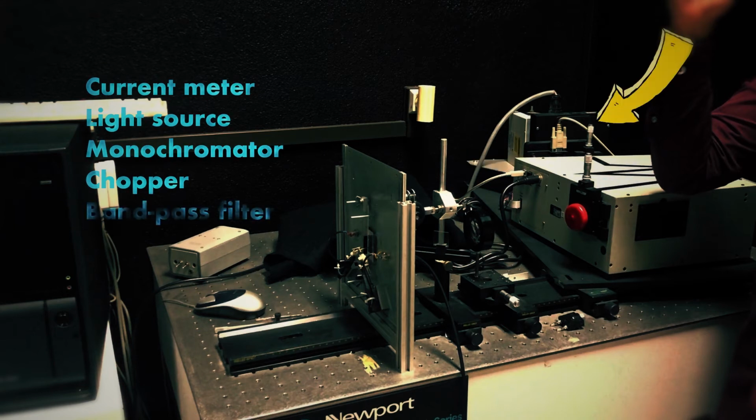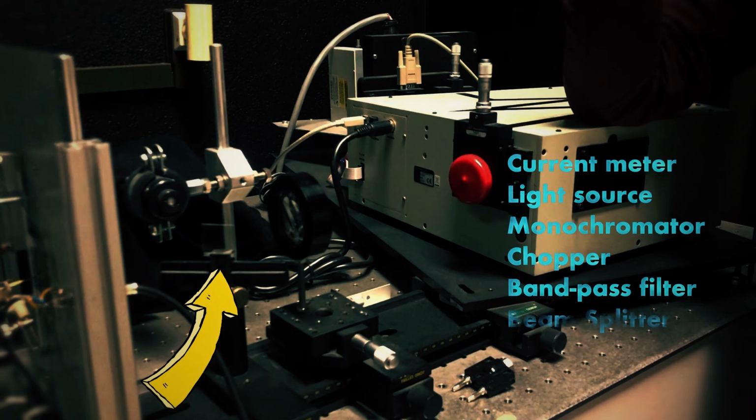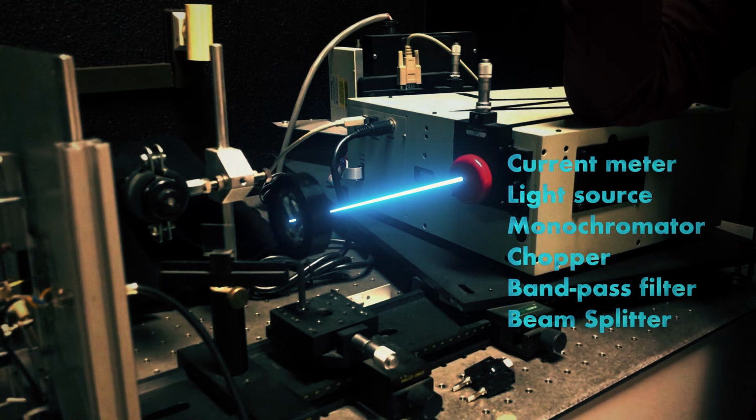A bandpass filter to cut off the harmonics of the wavelengths that, despite having a low intensity, can interfere with the readings. A beam splitter that divides the incident radiation in two, and each bundle of light goes to a different site, either the sample or reference detector. The latter has a known responsivity, so it is possible to determine the optical power incident on the reference detector and on the photodetector sample.